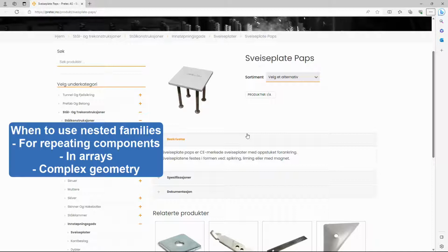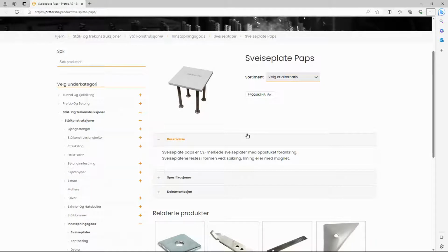Other advantages of using a nested family are that you can place a combined geometry and a rather complex setup as one single unit, where you want to control it as a whole in relation to other elements, and in general keep the family you load the nested family into cleaner and less chaotic, with fewer reference planes.